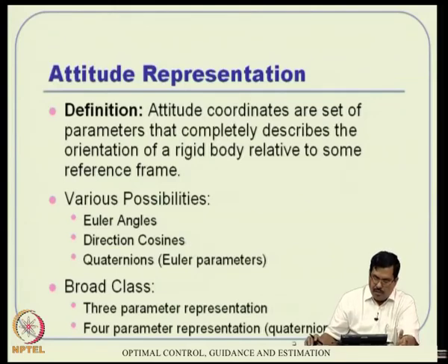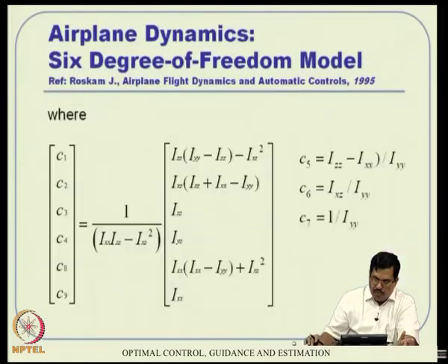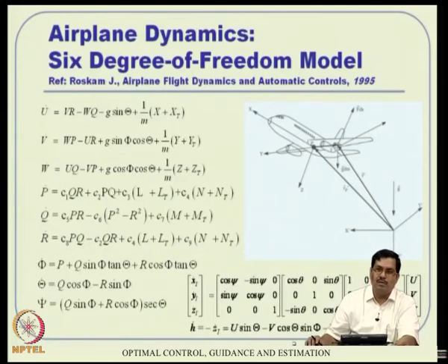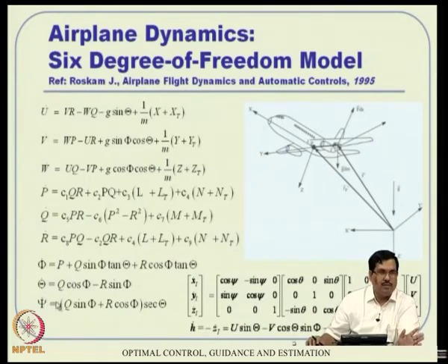And especially, okay, if you want to quickly look at that, I can also go there and come back probably. See this Euler angle representation, if you see it here, there is a tan theta term involved. Okay, right, what you see here, and tan theta is sin theta by cos theta, and here is a sec theta which is also 1 by cos theta. So that means if theta goes to 90, then the cos theta becomes 0, and there is something divided by 0, which means these rates will go to infinity. That is something called gimbal lock actually. That means no matter whatever degree of accuracy you use, delta t, take it to a very small quantity, even then the integration cannot be done. These dots go to infinity.